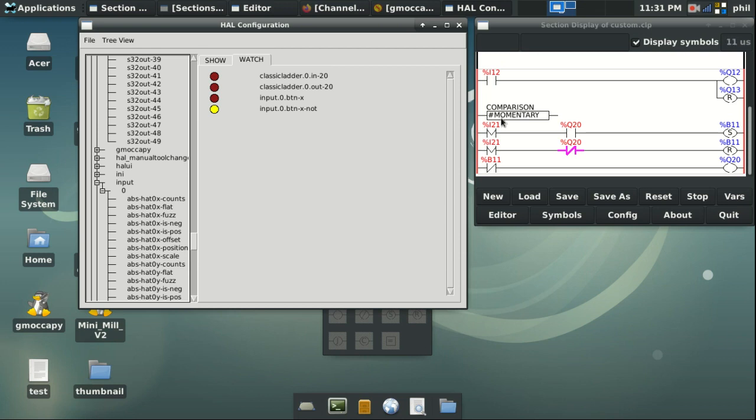So what I mean by that is right now I've got my I-21, which is set to a falling edge input with a normally closed switch. So using that, again, when I press the button, it instantly triggers the change.